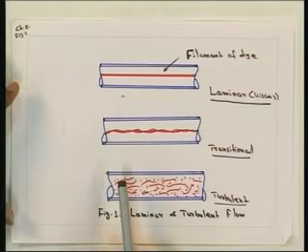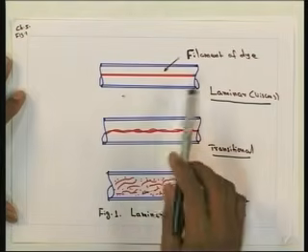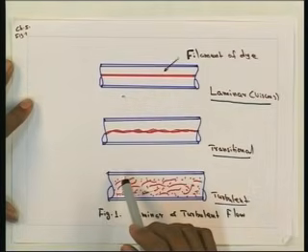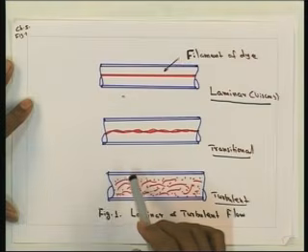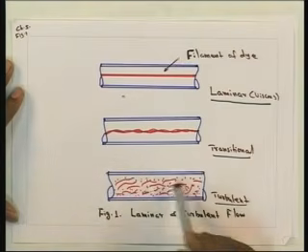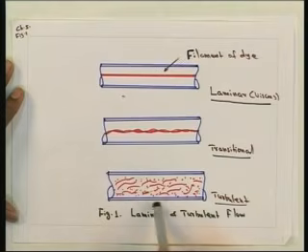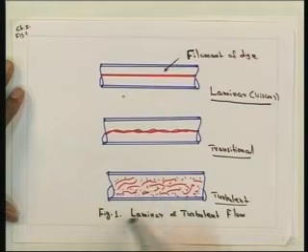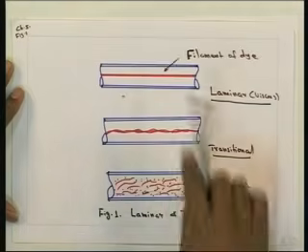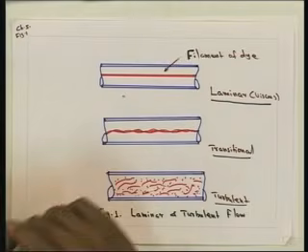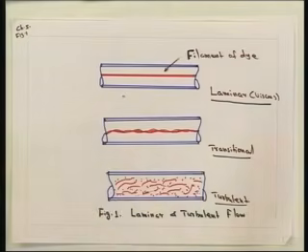As far as diffusivity is concerned, in the case of laminar flow, molecular diffusivity is more important, but in turbulent flow, the turbulent diffusivity is much greater than the molecular diffusivity as the flow changes from laminar to turbulent. Some of the other important characteristics are a high Reynolds number, as we have already seen, and in many cases the flow may be rotational in nature.